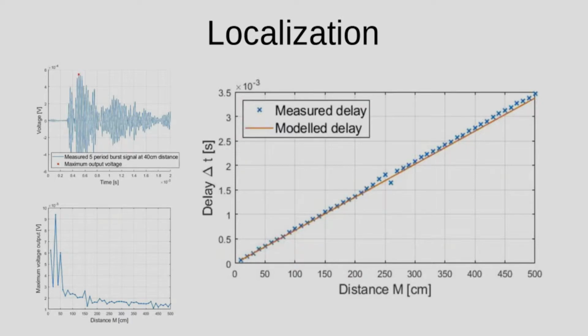So we used ultrasound, but the problem with ultrasound we found was that in some cases it works quite well. But unfortunately, especially in pipes, we had a big problem because in pipes, there's a lot of reverberation. We see a lot of echoes. And we found almost no correlation between the time that it took for a sound to go from one sensor to the other and the actual distance.